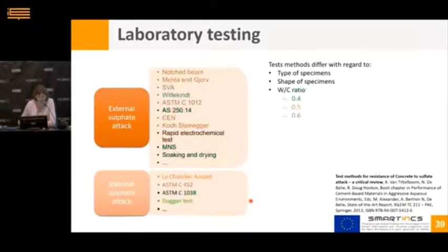If we then look at the water cement ratio that is applied, yes, here you see some advice to use a water cement ratio of 0.4, 0.5, 0.6, but of course, if you take the same water cement ratio, but you change, let's say, the components in your mix, it doesn't mean that you have the same permeability of these mixes because they have the same water cement ratio. So in that way, there is also some discussion on this.